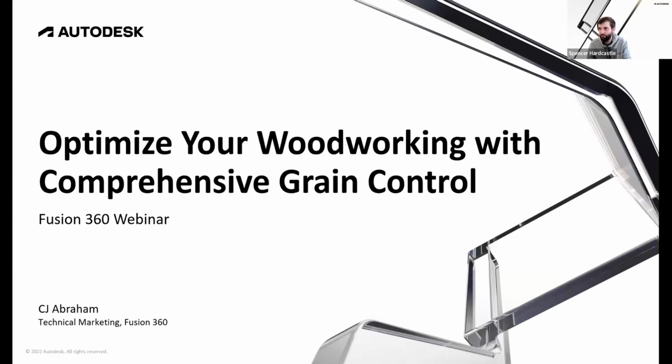We're going to be talking about optimizing your woodworking with comprehensive grain control. Grain control is a new feature that we've added in Arrange and Nesting Fabrication. It allows you to control the direction of the parts, the orientation inside of the material, so that you can match the grain with what you want it to be.